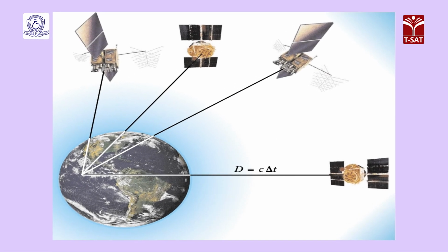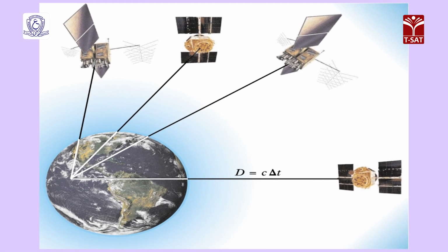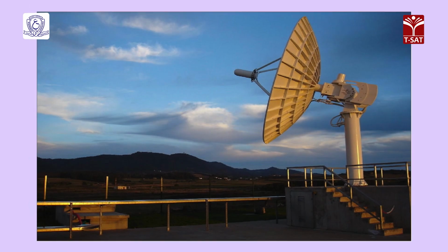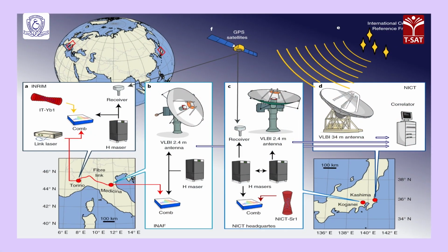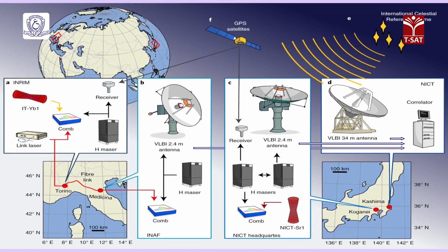The master control station then periodically sends the corrected position and the clock timing data to appropriate ground antennas, which then upload those data to each of the satellites. Finally, the satellites use that corrected information in the data transmission down to the end users. This sequence of events occurs every few hours for each of the satellites to help ensure that any possibility of error creeping into the satellite positions or the clock is minimized.